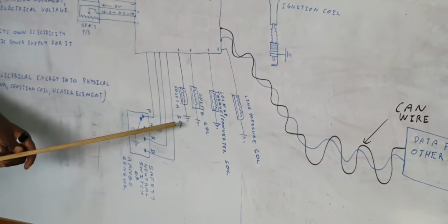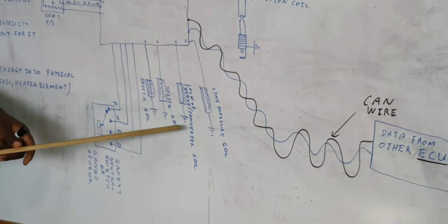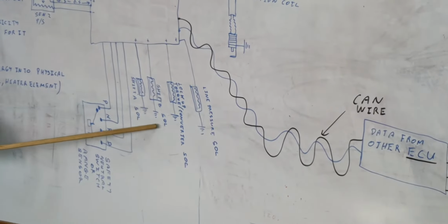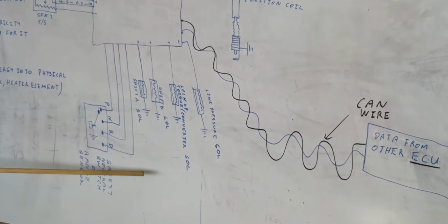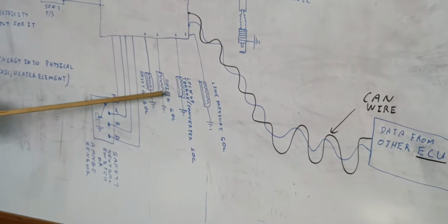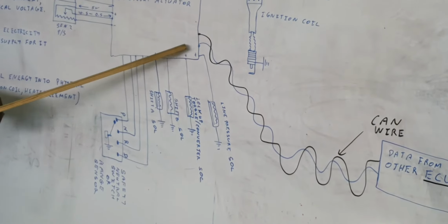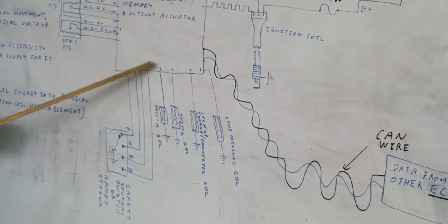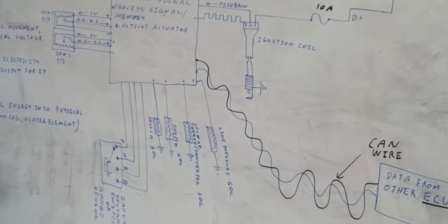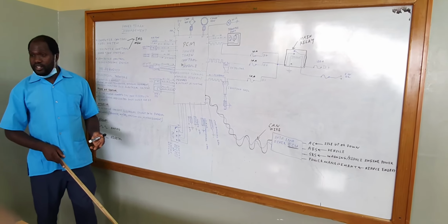And what comes out of the ECU, you notice a shift A solenoid, shift B solenoid, torque converter lockup solenoid, line pressure solenoid. All of these solenoids are grounded to the frame of the transmission. So from magnetism we have gone to this. These are the coil winding and the core. So with these solenoids now, a plus will be coming out of the automatic transmission to activate them. A 50-year-old technology, a 70-year-old technology, you know.